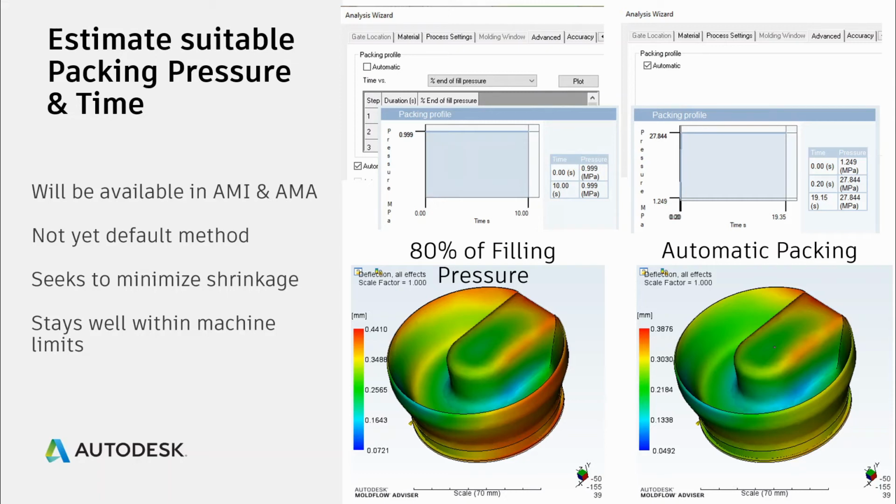Now, of course, if you have exact molding conditions, if you have already molded parts and you know what the packing pressure profile was, then it's always best to enter the exact process details. But if your design is at an early design stage, you do not yet know how the part will be processed, you do not know what the suitable packing pressure is, and you're just trying to gain an idea about how the part will perform and what its shrinkage will be, it may be that the automatic packing profile is a more reasonable estimate for you than using 80% of the filling pressure.